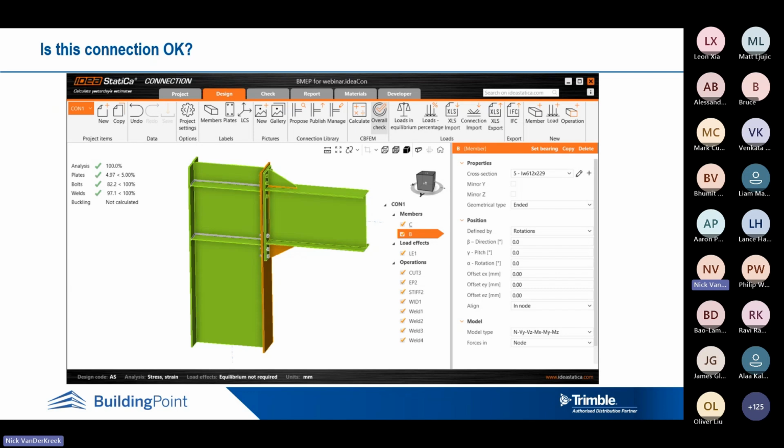So I just want to move to an illustration of a knee type connection. If I had a little bit of slope on the beam, this could be a knee in a portal frame. I could easily adjust the slope in the software, or it could be a regular floor beam or something like this, a horizontal beam as I have in this case. So I've added the members, the connection details, one load case, you can have as many as you like, and I've pressed calculate, which performs the analysis and gives us a summary of the result.